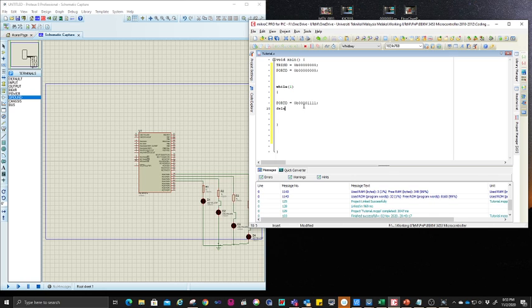And you have to put a delay. This is just to delay it, delay_ms. This is a function to delay it for 1 second. Then you turn off port D back using the PORTD command with all zeros, and you have to delay again, delay_ms 1000. So you can see that this is the loop that is going to be executed: from here, turn on, delay, turn off, delay, go up again, and this happens continuously.